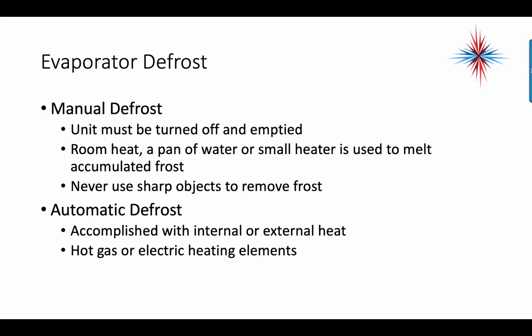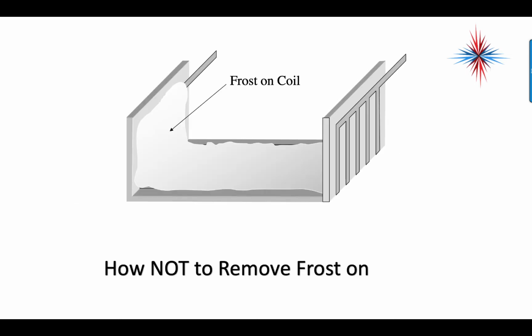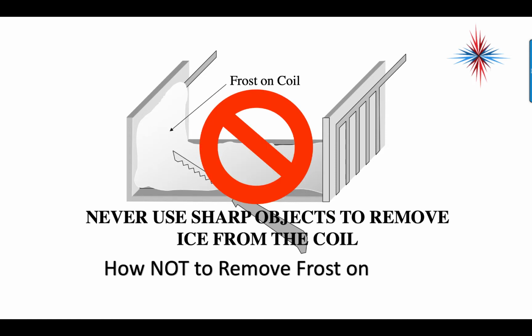Automatic defrost is accomplished with internal or external heaters. Sometimes we use hot gas, and we also could use electrical heating elements. How not to remove frost: don't use serrated knives on coils. These things are aluminum. A knife will go directly through.